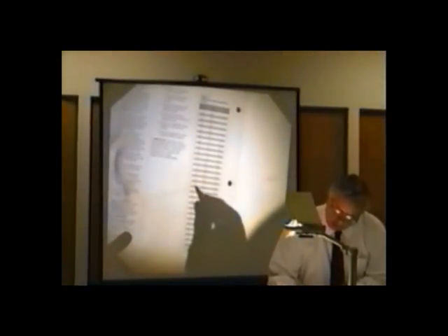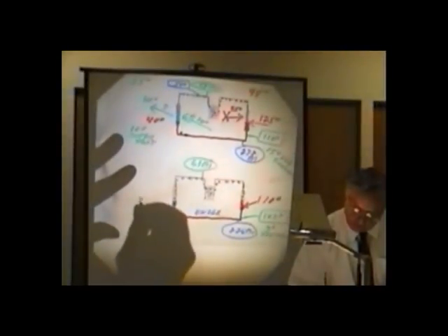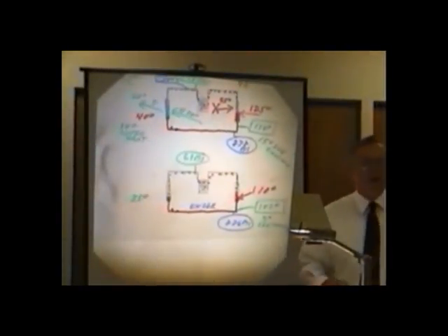I'm going to come over here now and I'll say that I now have a pressure reading of, I think it's 61 psi. Let me take a look at my pressure chart. If I have a 61, 35 degrees, do you see that? 61 psi is 35 degrees on my saturation temperature. So watch this now. I now have a 35 degree evaporator. Guess where it's 35? Only where the liquid is.